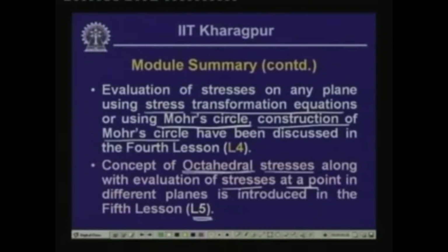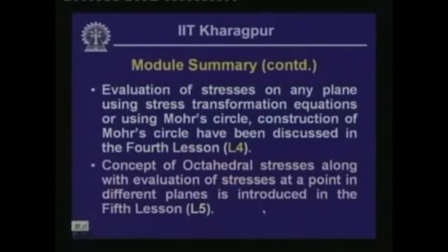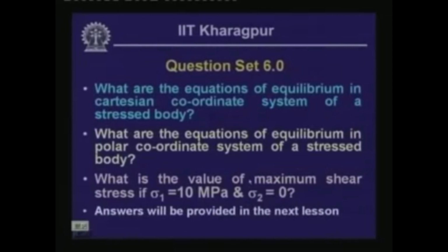And as I have told you, the octahedral stresses act on octahedral planes which are equally inclined with reference to the principal axis system, and these stresses are useful when we talk about the evaluation of stress in the inelastic stage. And in this particular lesson, we have tried to give you the concept of the stresses in a polar coordinate system that you have already looked into.